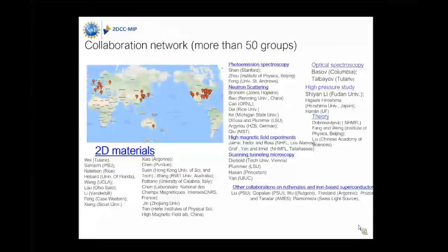So would it also be applicable for a solid substance, like if you have an amorphous substance and you heat it to a high temperature and then cool it really slowly? Yes, that is also applicable. If you have polycrystalline material with some micrograins, then you have to cool down very slowly for a long time, much longer than the solution growth. And then if you're lucky, you also get a good single crystal. Yeah, we did that before.